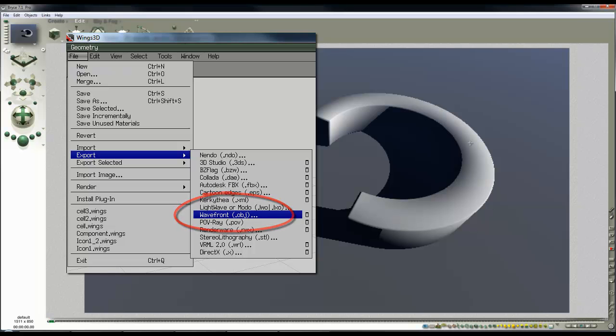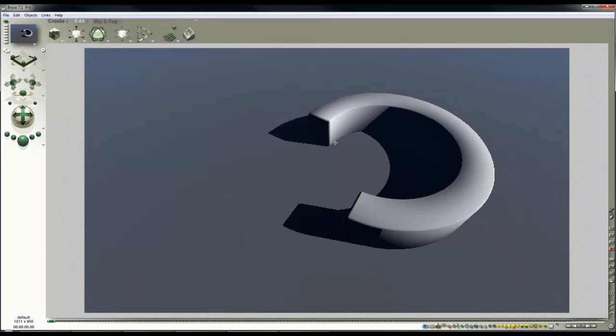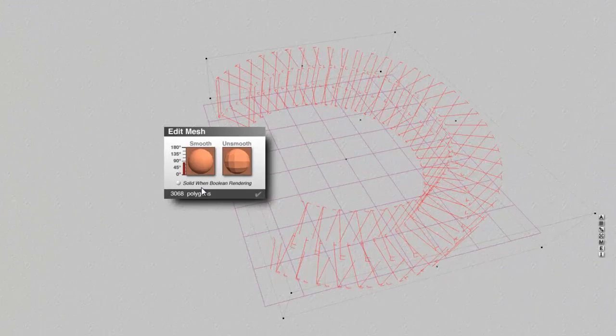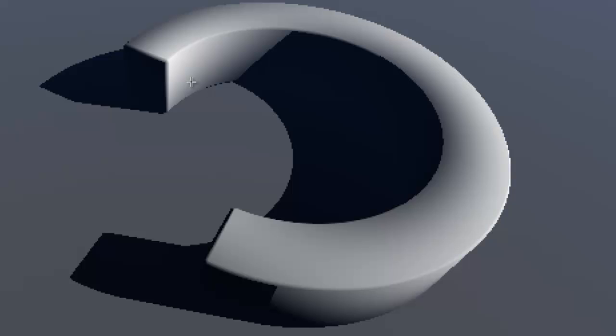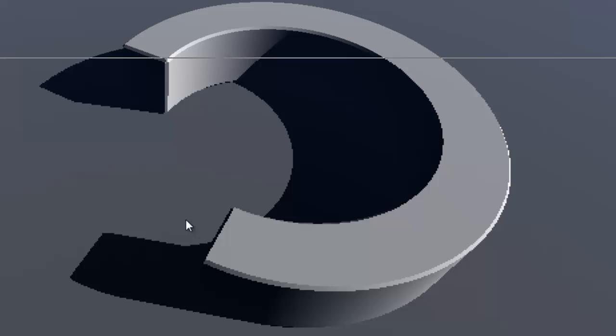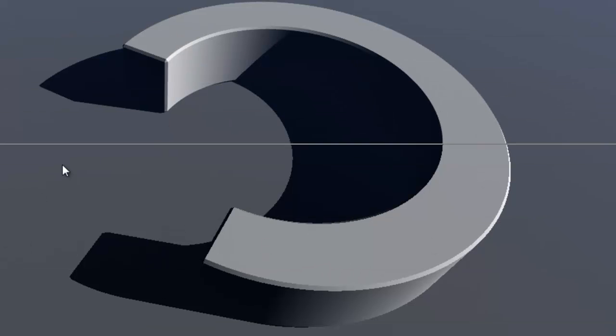and this comes in automatically smooth, but the smoothing that's applied is not appropriate, so I'm going to have to edit that. If I lower this angle here, it will respect the corners, but it'll still smooth the inner curve, I hope. So I've got smoothing on the inner curve here, but I've got corners and flat surfaces now, so it's just suiting the geometry that I need for this.